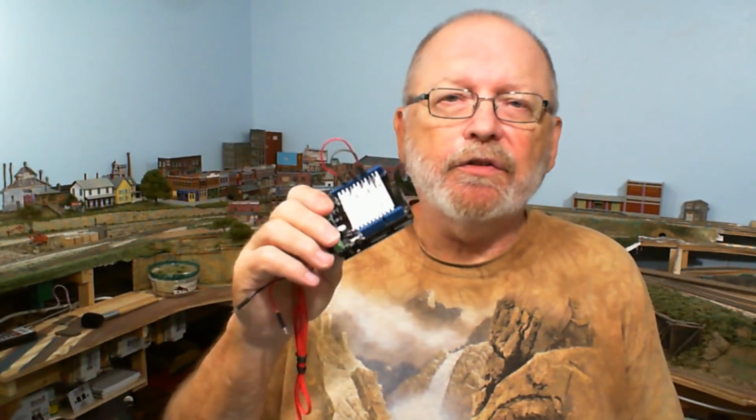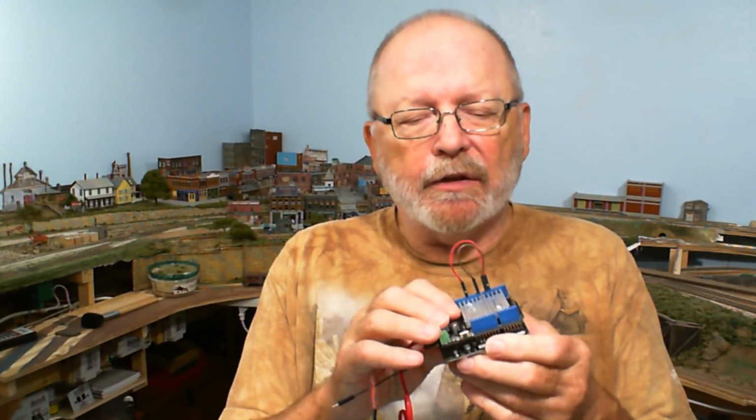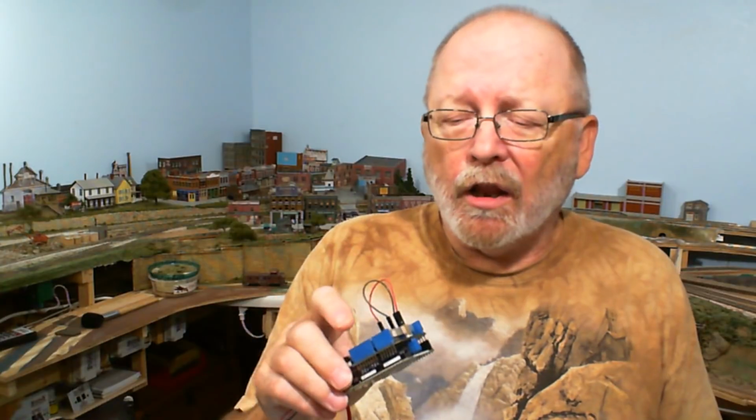I've spent the past couple of days working with my Seed Studio motor shield. Now, this isn't a cheap one. I looked it up, and now they still sell it, and it goes for about $19.95. There's other motor shields out there that go for as low as $5, $6. You want to stay away from those. A lot of them don't use the L298 IC. It uses the L293, which is less amperage.